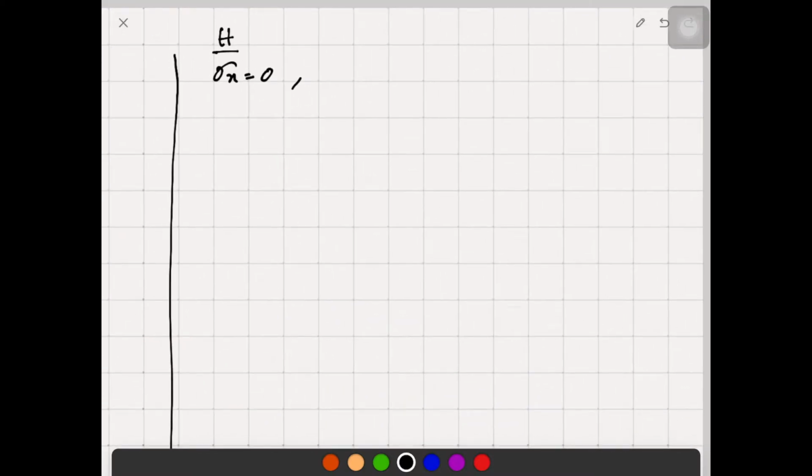I hope that is understood by now. This is the second part of solid mechanics. Next is sigma y for the system. Due to bending, this is My over I, and in this case it is moment x times the radius. We don't have y for a circle, so I'm going to replace y with r, the outermost radius.